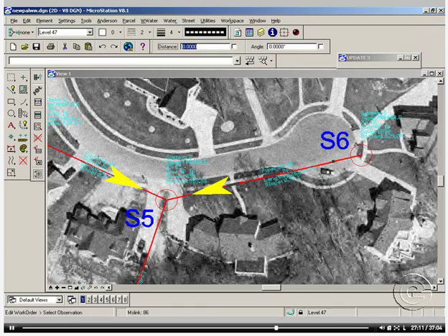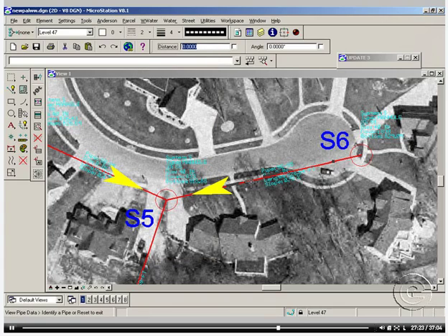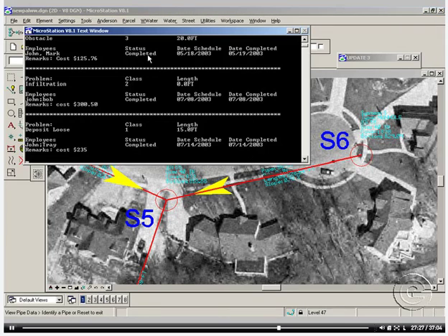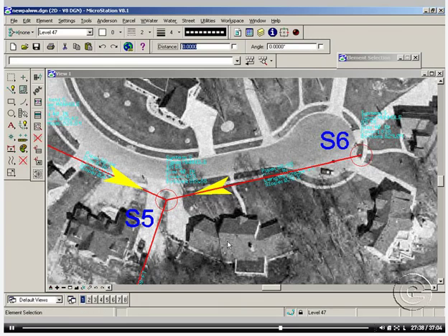And as we do have those problems, we could go into the program and see sometimes how many problems we have fixed on a specific pipe or whatnot. And we can go and choose view pipe work orders, and then click that, and then go in and type in tag a pipe, accept it, and as you can see, the program will bring in a MicroStation text window here that shows the pipe that we've selected. Let's say S6 and so on.